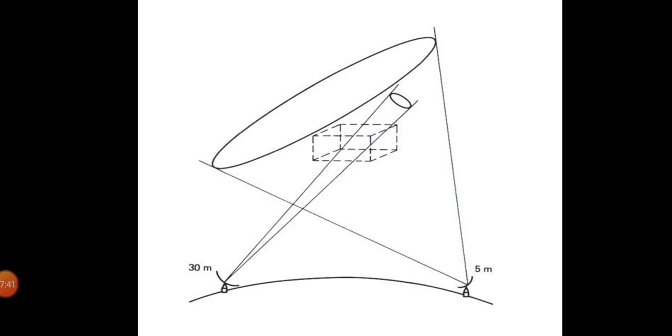Thus, both the latitude and longitude sides of the box will be around 147 kilometers, and the situation as just shown in this figure also shows the relative beam width of a 30 meter and a 5 meter antenna. As you can see, the beam width of the 30 meter antenna is about 0.12 degree, and of the 5 meter antenna about 0.7 degree at 6 gigahertz.